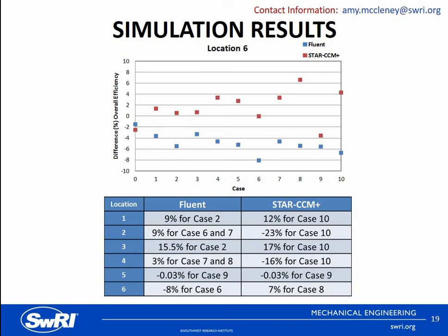However, both tended to perform reasonably well, and were able to predict a separation efficiency within plus or minus 10%. And that was because we initially did all these different sensitivity studies to choose the best multi-phase modeling approach, as well as the best submodels that would provide us the most accurate result.